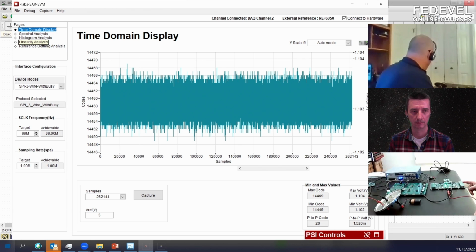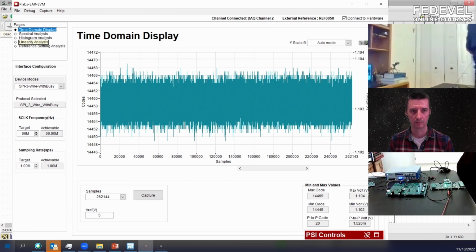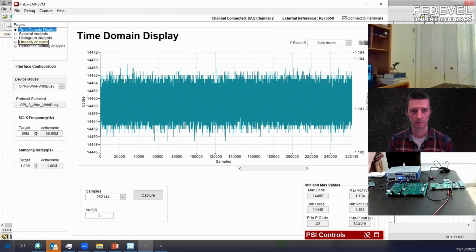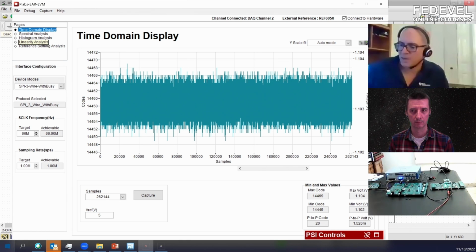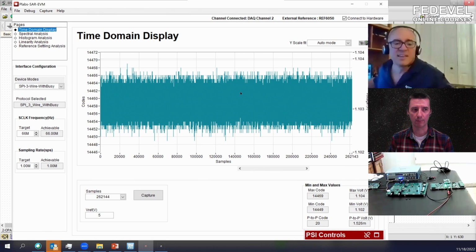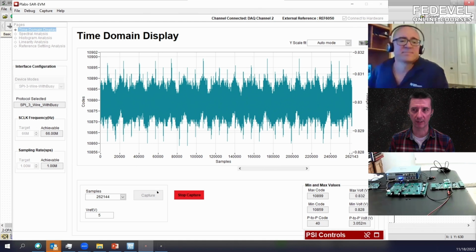You'd want a shielded cable, but I'm intentionally making things bad, so I have these wires all spread out, and I'm going to move this over by my lamp, and so it's going to be a really bad situation that you don't want to do, just to illustrate the 60 hertz pickup. So basically, we have a battery connected to the AD converter, but through very long wires.